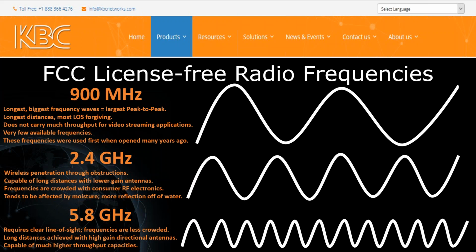And so the products that you use have a little label on them that basically tells you what it's able to do. And one of those things is that it has to accept all forms of interference that may come from other devices that are using these same frequencies. And if there is, then you have to change frequencies, or you have to align differently, try to get away from what's interfering with you. You can't try to overpower them in some way. So you have to stay within the legal parameters.